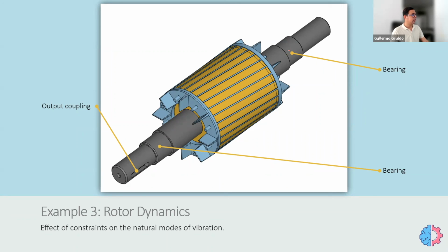So say, for example, that all I do is fix this end face. Of course, that will get rid of the rigid body motions, but will it be realistic? If you think about the torsional rigidity of the shaft, it's not the same if you fix it here and here, with this length, as if you fix it somewhere else. Because if you reduce the length, then the stiffness will not be the same, and you will be affecting the stiffness and the natural frequency. Same for the bending modes.